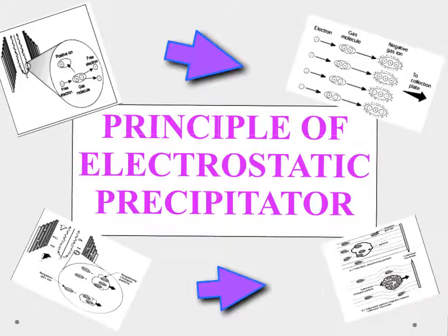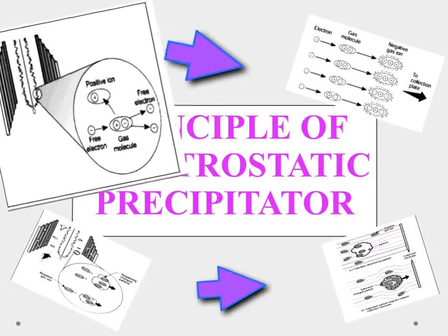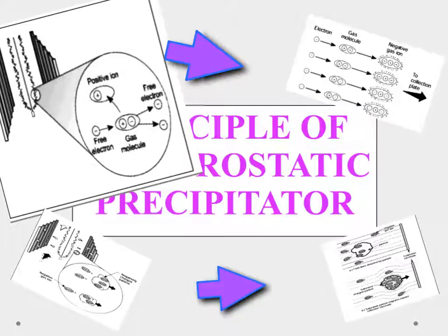After finishing talking about the basic components of electrostatic precipitator, now let us talk about the working principle of electrostatic precipitator. There are two stages. During stage 1, the electric field is established due to the DC terminal arrangement. The applied negative voltage in the discharge electrode is increased until it produces a corona discharge, which can be seen as a luminous blue glow around the discharge electrode. Due to the formation of corona discharge, free electrons are emitted with high velocity from the discharge electrode.